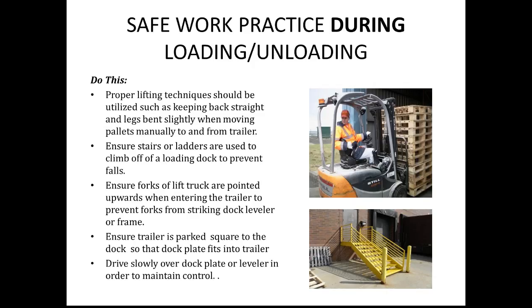So they would park the forklift off the dock plate, isolate it, take the keys out of it, then go in and properly lift maybe a couple of falling over pallets. They use proper lifting techniques, which is straight back, legs bent, and obviously if the weight is a little too much for them, they get somebody to help them do that. It's surprising the number of people that get injured trying to reposition product or pallets that have shifted in transit inside the trailer.